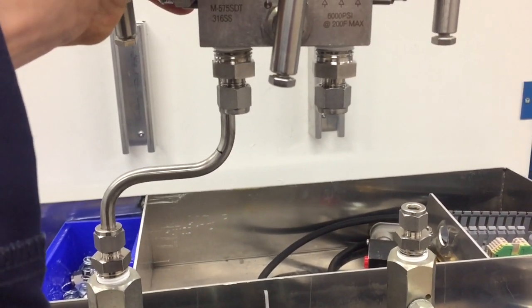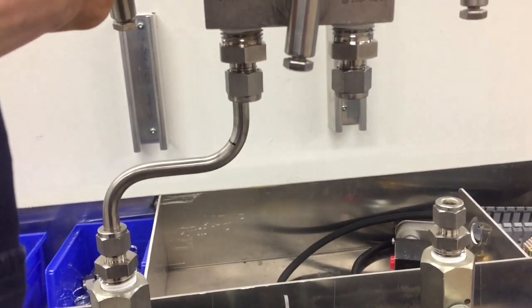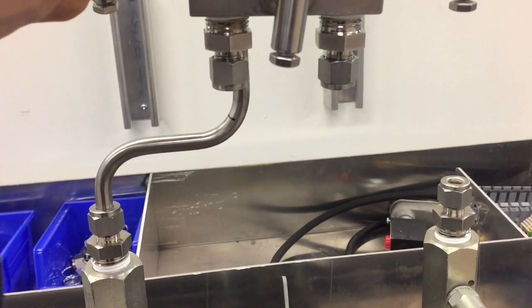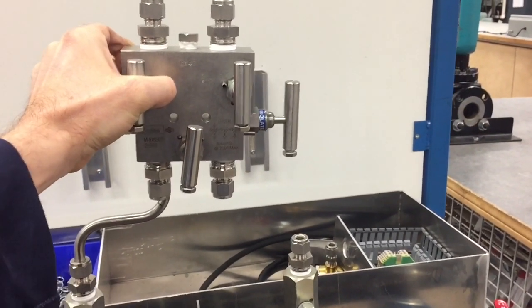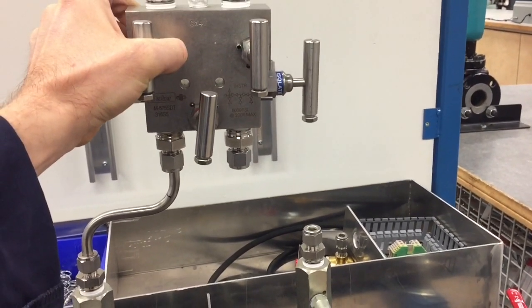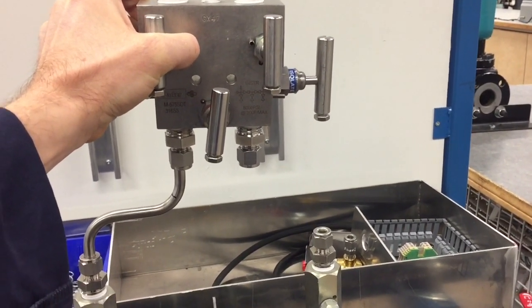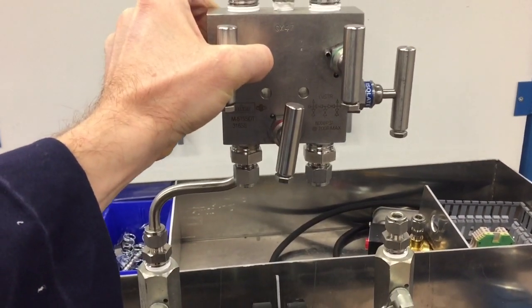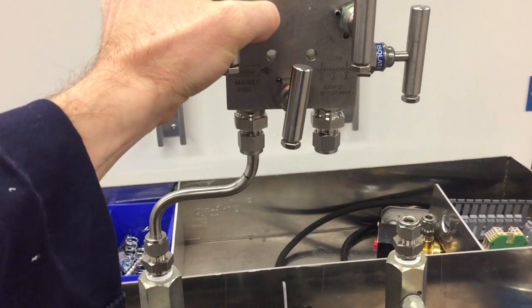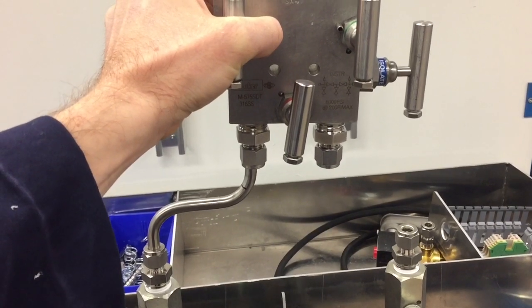Right, so I have the tubing installed. We're going to be cutting off some of the tubing. We're going to make sure that we have enough of the straight run for our tube fitting, but really the height of this is probably going to be the deciding factor. We don't want this too high, obviously. We want it to be probably about chest height or so. So we'll just nip it off and make sure we have enough of the straight run.